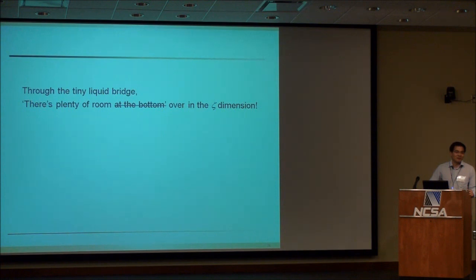Can you control whether you're growing single crystal or polycrystal metal? Not for every type of metal. For some types of metals, there's an existing process that allows you to grow single crystal. But we haven't tried those epitaxial approaches. Suppose you have a pure single crystal metal surface to start with, or a highly doped single crystal semiconductor to grow on, we may be able to do epitaxial growth. But if you just use a regular polycrystalline film coating, there's only a limited selection of metals that allow single crystal growth.